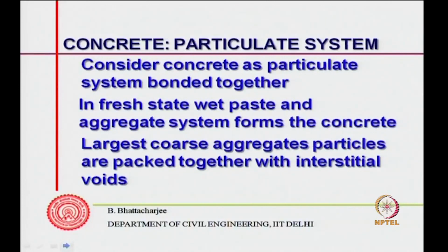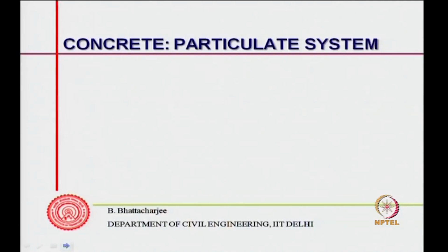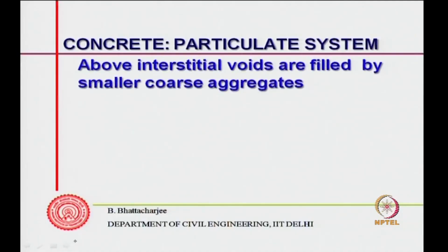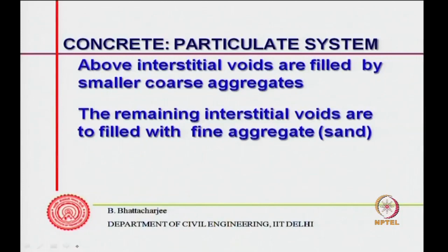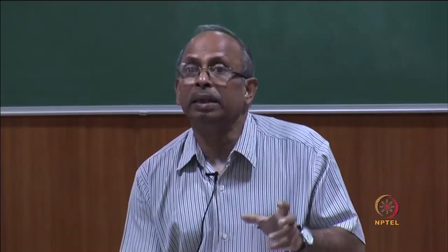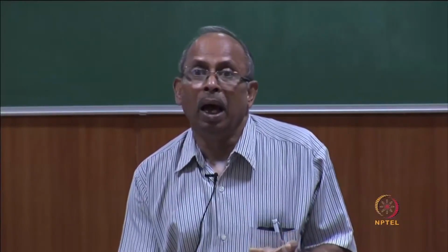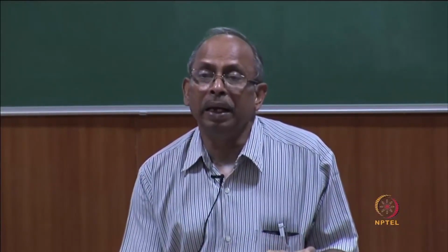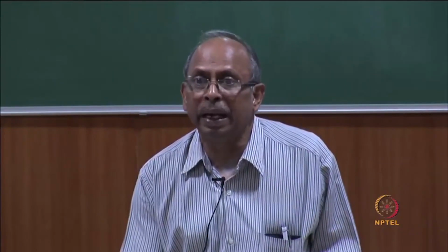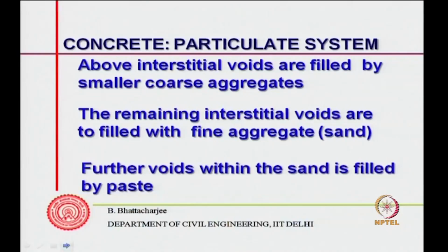Largest coarse aggregate particles are packed together with interstitial voids, and these interstitial voids are actually filled with smaller coarse aggregate, and the remaining interstitial voids between the larger size particles of coarse aggregates are filled with fine aggregate. Quite often they could be natural sand or crushed stone, etc., as we have discussed earlier.